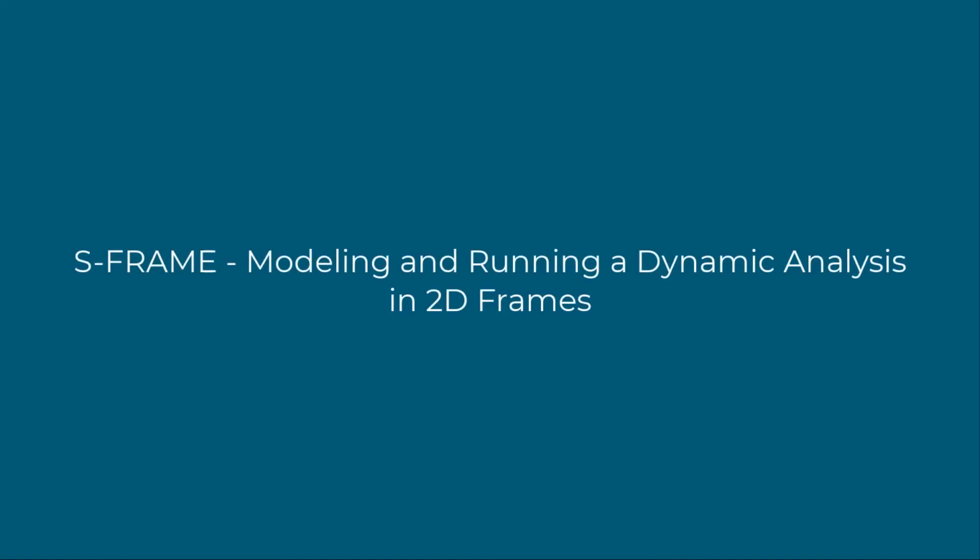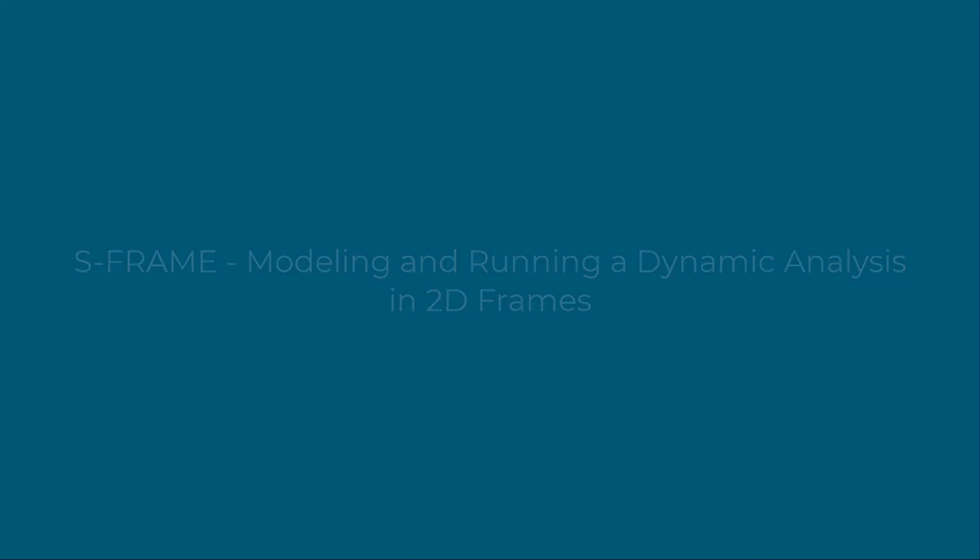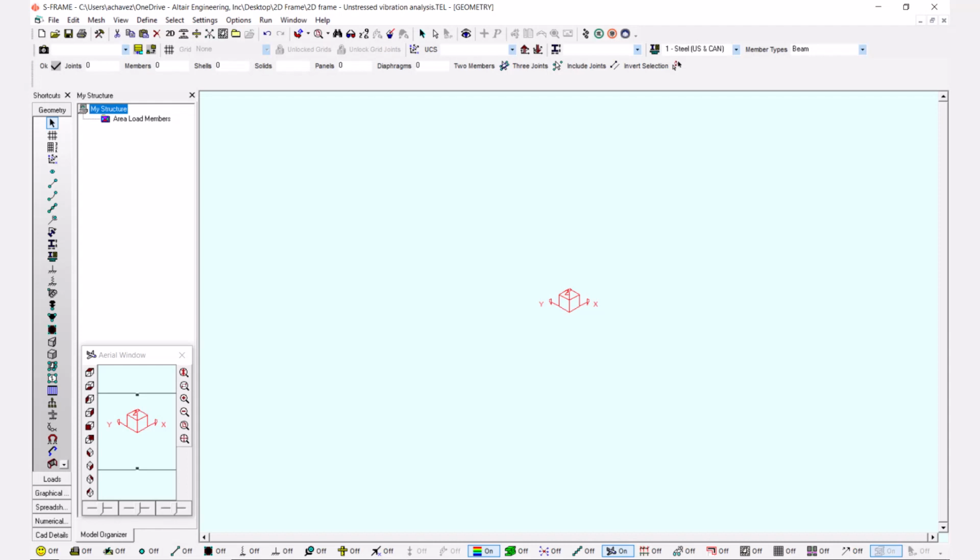Join me in this short video to learn how to model and run a vibration analysis on a simple 2D shear building in S-Frame. We will be following S-Frame's general workflow for today's exercise, meaning that we will first define our structure's geometry by creating all the different nodes, members, and elements that comprise our 2D frame. Then we will be applying material and section properties to all these newly created elements.